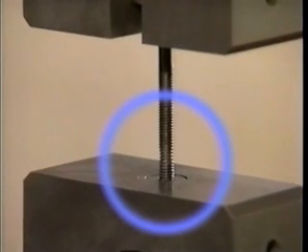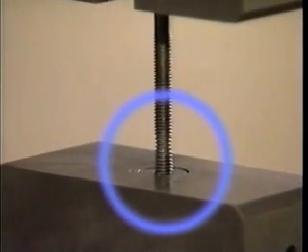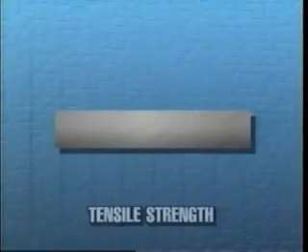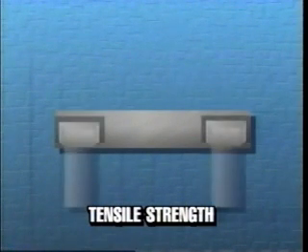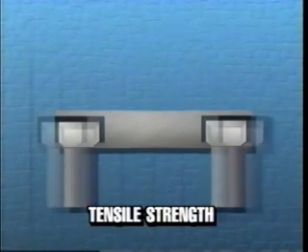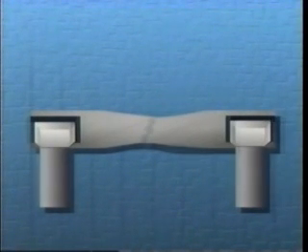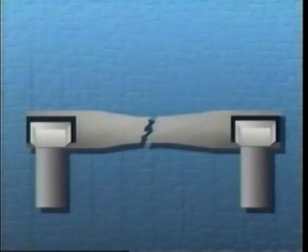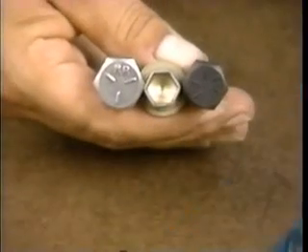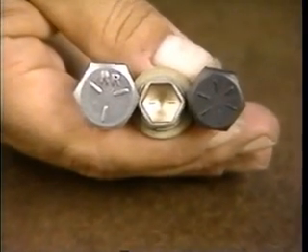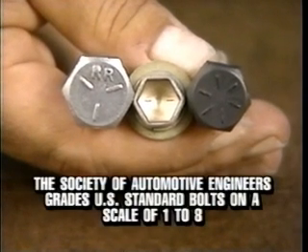The strength of a bolt varies with the materials and heat treatment process used in manufacturing. Tensile strength is the rating given to the steel used to manufacture the bolts. A test machine pulls on a steel rod until it breaks. The tensile strength is how much force the machine used to break it. A system of grading allows the bolt strength to be identified.